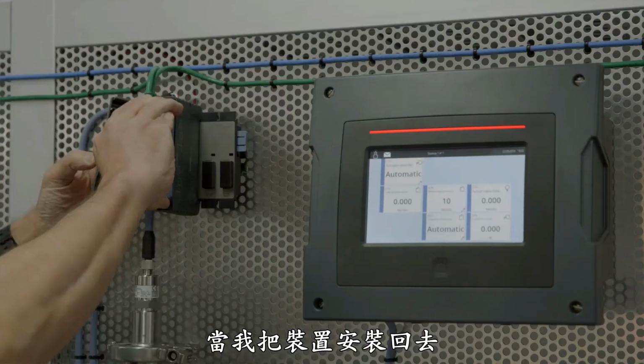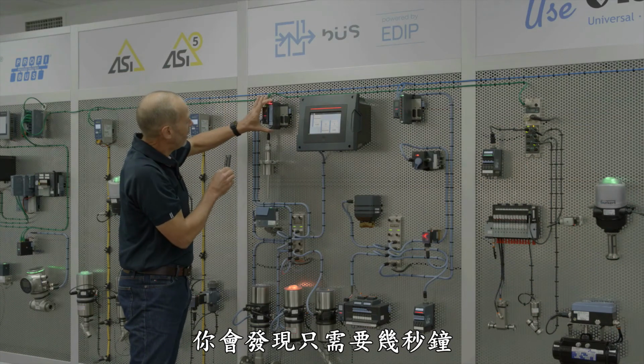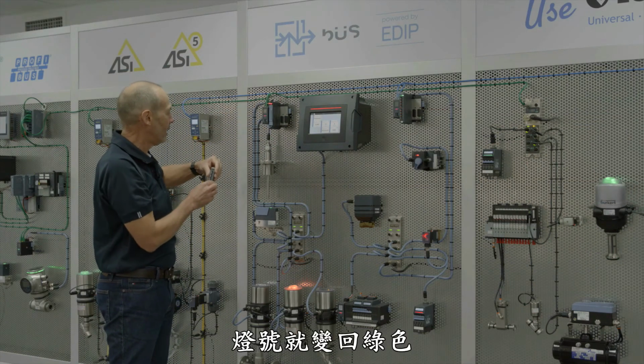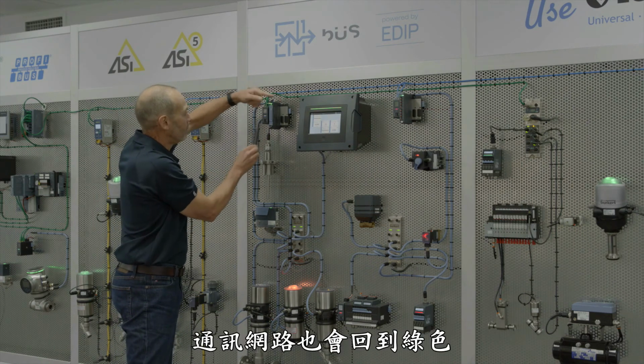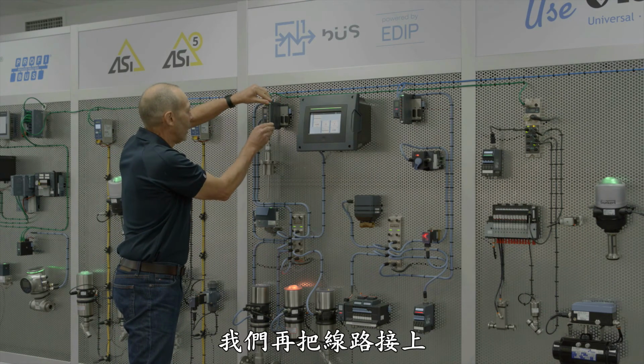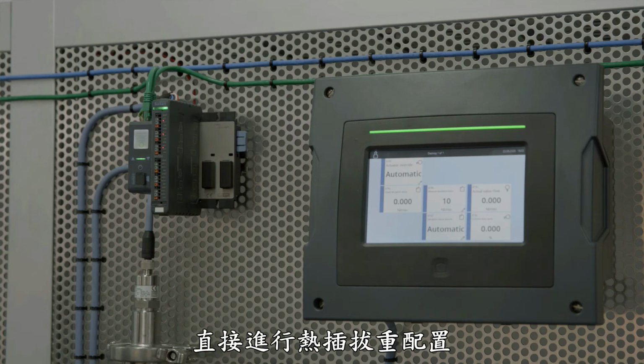By reinstalling this, you'll notice that it only takes a second and it goes back to green. There it is, which will then put the network back to green, and then we can plug our wiring back on. And now we've just replaced a complete I/O module online in a hot swap configuration.